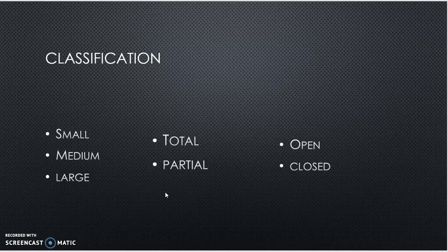And partial prefabrication will be mainly talking about roofing and flooring units being prefabricated. Walling and columns will be cast on the site and then interconnected to the roofing and flooring units. So half of the thing is cast in situ, half of the things is prefabricated. In that case, you call it partial prefabrication.